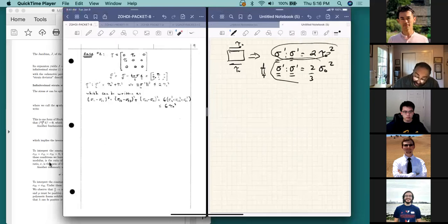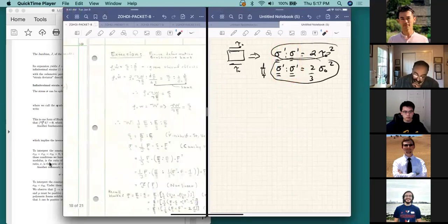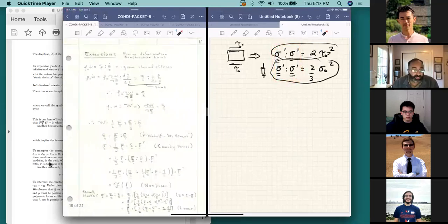Now there could be conceivably others, but the common theme here is that the magnitude of how big the deviatoric stress is, is considered the first possible angle of attack to go after describing some kind of nonlinear behavior. Okay, so that's where we left off. And of course, what I want to do now is to basically extend these kinds of laws to see exactly what are those kinds of constitutive laws that go into the finite regime.